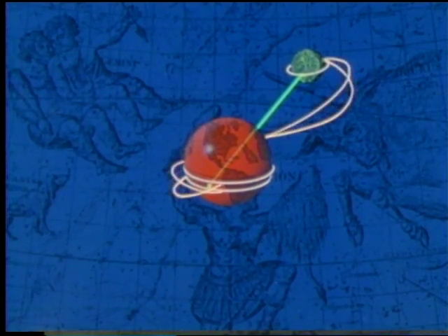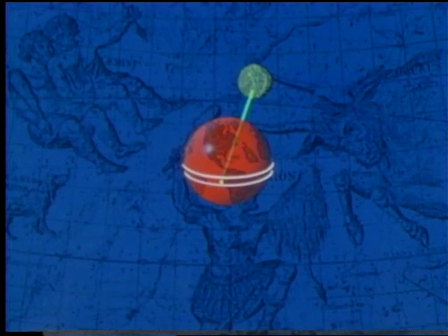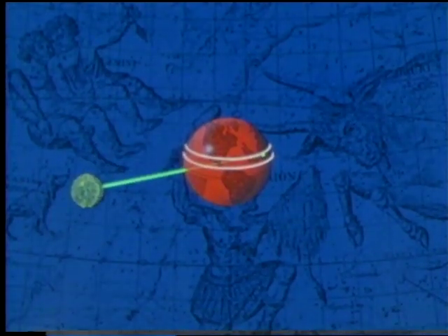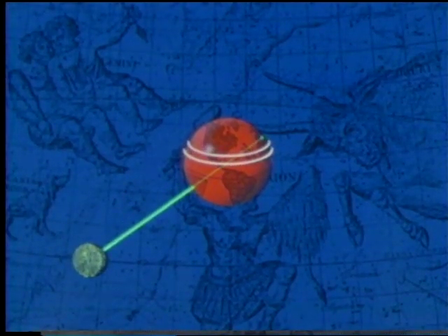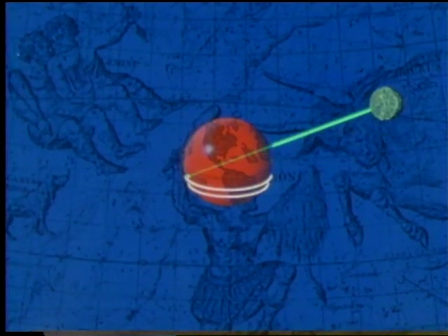While latitude range is determined by the possible range of return trajectory planes and the entry range, the location of the latitude range is determined by the declination of the moon. As the moon changes its declination throughout the month, the latitude range shifts accordingly across the surface of the Earth.